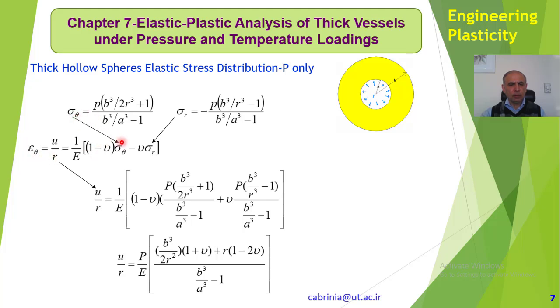So if I put sigma theta here, sigma r here, and obviously epsilon theta is u over r, so I can get the displacement as well. Therefore, as you can see here, everything is known, and I can have the displacement in terms of r. In other words, starting r equal to a up to r equal to b, any intervals between b and a in here, I can have the displacement due to the elastic stresses in here.